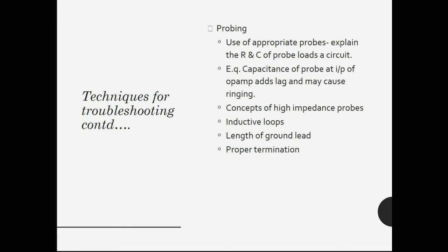It is generally accepted that for general purpose, that is mid to low frequency measurement, less than around 500 megahertz, high impedance passive probes such as 10:1 are the most suitable option. Often the choice of scope probe that is used will depend on what is available in the lab. However, for most applications, the 10x probe is the best all-round type of probe.